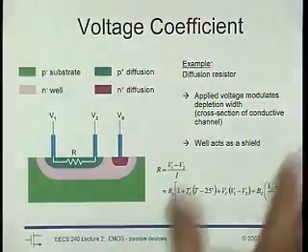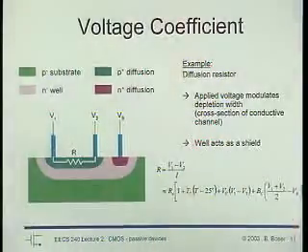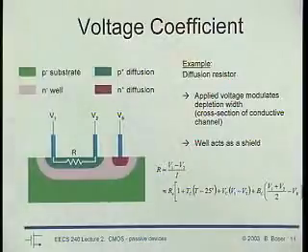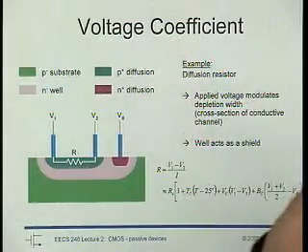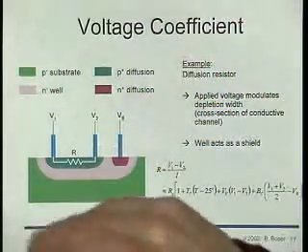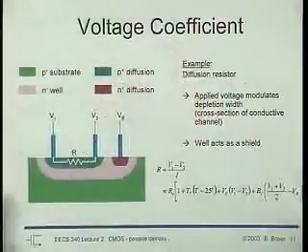Well, the substrate is shared by everybody. Every circuit goes into the same substrate. And every circuit invariably is going to inject a little bit of current, electrons, carriers, into the substrate, and they produce voltage differences. And these carriers also ultimately get sucked up by something again, right?